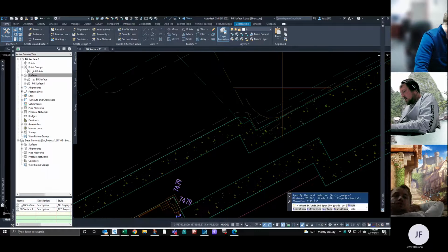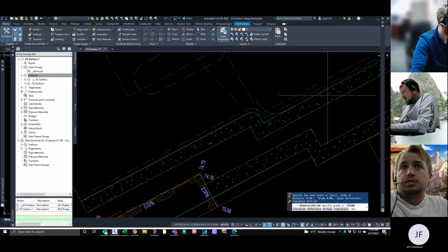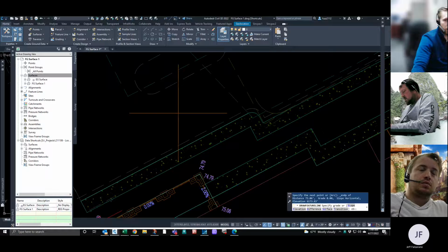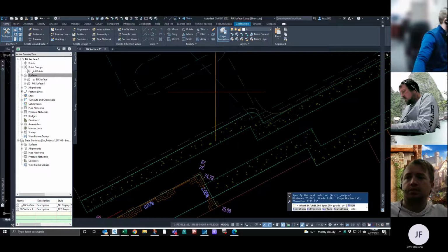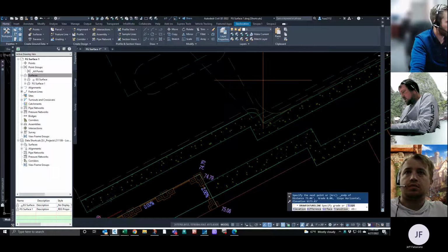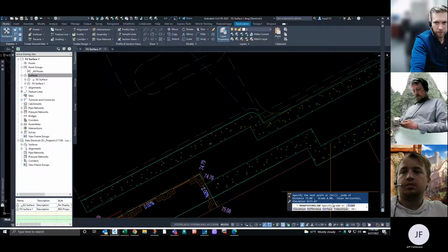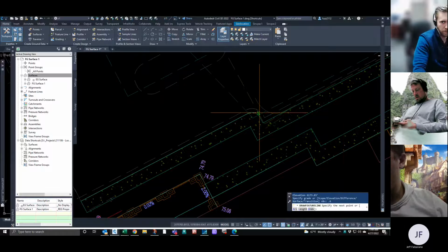Endpoint. Do we know the slope, or do you have the elevation, because we can do it by slope or elevation. So the slope of the flow lines, let's just say that matches. I see where you end. It's 0.6 towards the east, so we're going uphill. So it's defaulting to grade here. In this case, we just want to say 0.6 because it's going uphill. If it was going downhill, it'd be minus 0.6. So we just hit enter there.